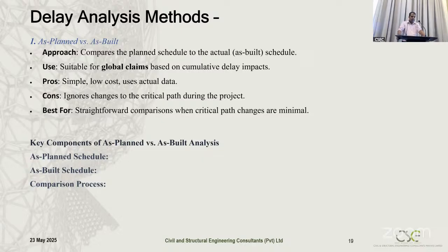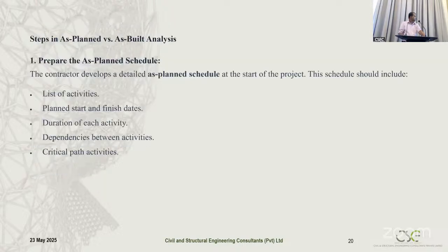Then we assess the total impact of these delays on the overall project duration. In the as planned schedule, I explained the list of activities, planned start dates, duration of each activity, dependencies between activities, and the critical path activities. We are focusing on these things.